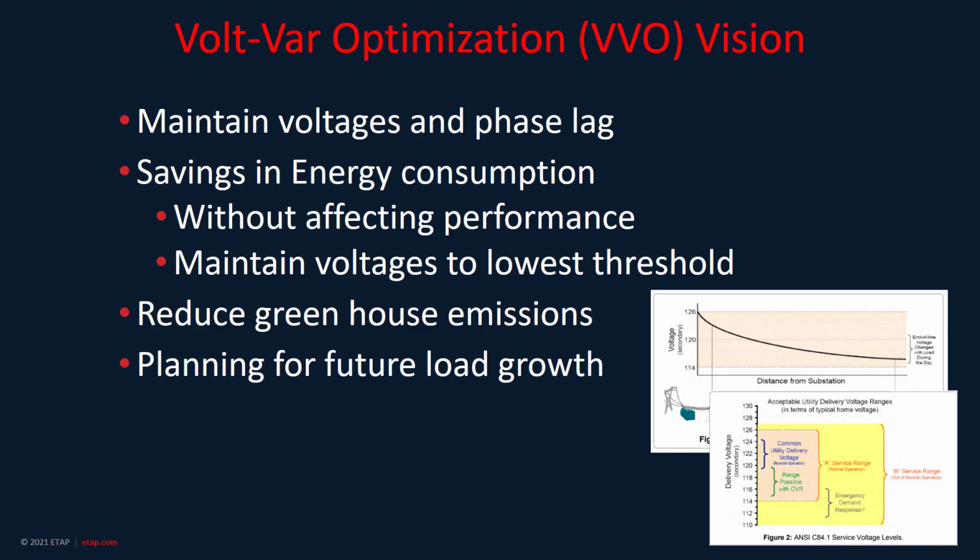It is a centralized volt-var optimization for a distribution management system, DMS. The main objective of volt-var optimization control is to make the distribution grid more efficient by decreasing power loss and to reduce utility costs by reducing peak demand or through conservation voltage reduction, CVR.